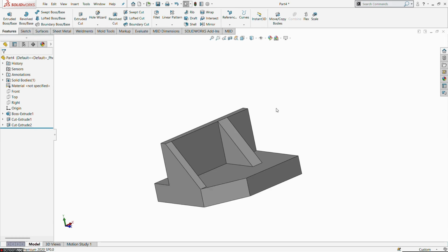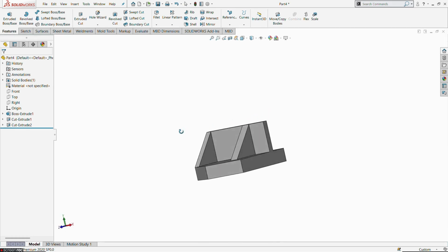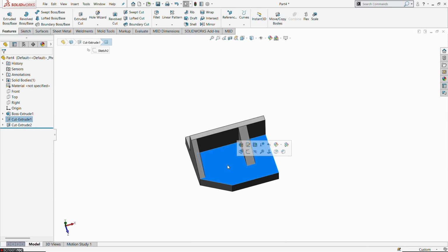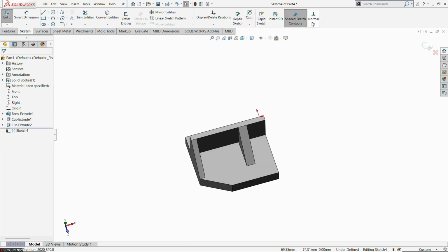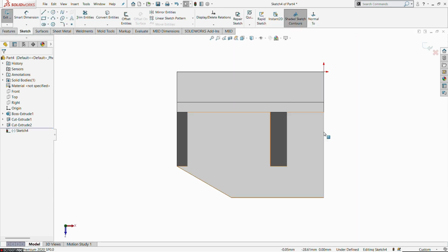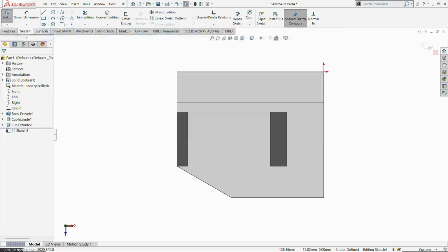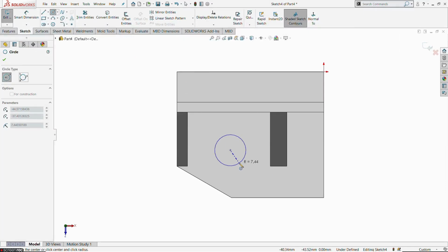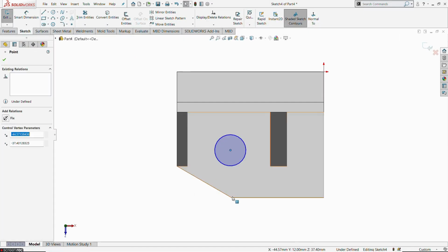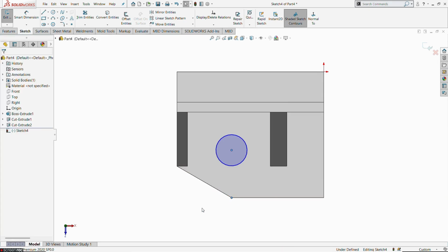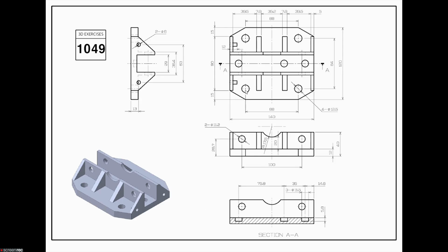Once we create the pocket, now select the top faces and draw another circular profile. Let's form circular profiles at different portions to make a proper one. First, the initial circular profile. Start from it. We need to either position the profiles or give the overall dimensions. First, select the center point as well as the endpoint to fix it linearly in a vertical direction. Now it is exactly placed in the horizontal way also.